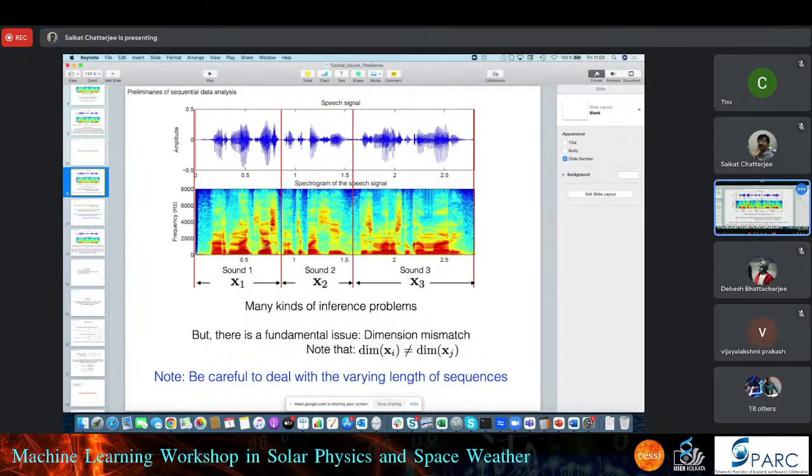And when I have a power spectrum, it is nothing but second order statistical parameters, which is the Fourier transform of autocorrelation values. So you basically assume that for this particular small portion of the window, this is a second order stationary signal, and then from there you do these analyses. So you see that the second order statistics of the signal is changing with respect to time. That is what time varying means.